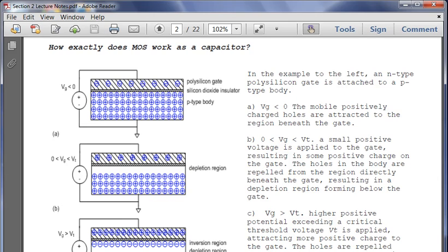We've now raised this potential beyond what's known as the threshold voltage. The importance of the threshold voltage is you need to be able to get that voltage at or above the threshold voltage in order for the transistors to switch. So once we actually create this, this is when we can start putting the transistors together. So you can see there's this kind of range where you apply your gate voltage, you actually have to raise it to a certain amount in order for the transistor to create a channel for it to operate properly.